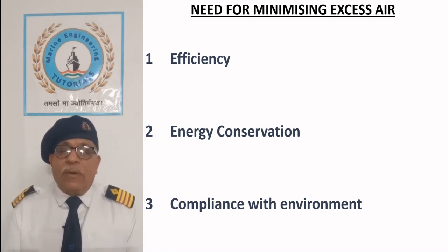Thus, it is important to strike a balance between performance and compliance with environment by optimizing the amount of excess air based on specific characteristics of the fuel being burned and the design of the boiler. This is often achieved through careful monitoring, control systems, and periodic adjustments to ensure both efficiency and environmental compliance.